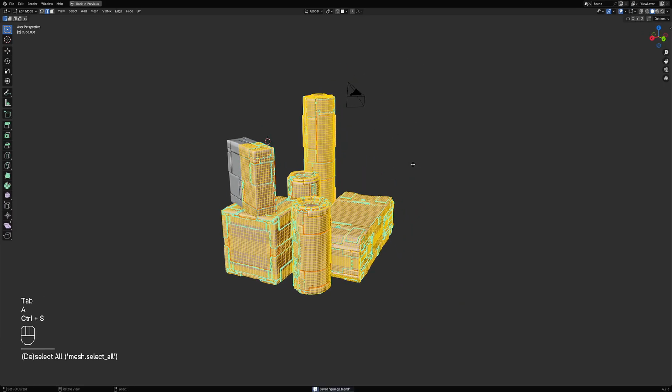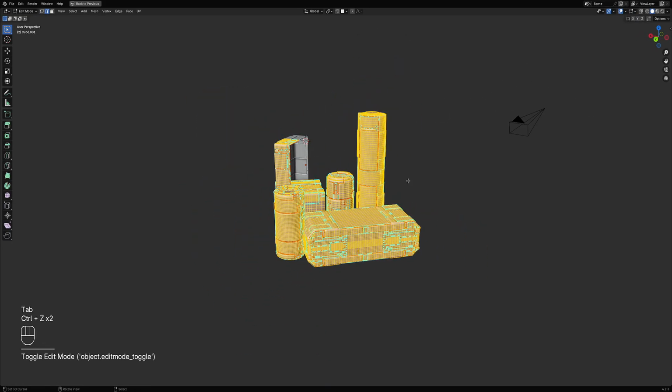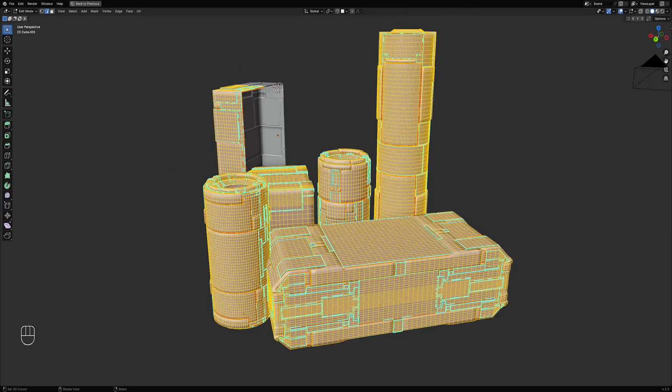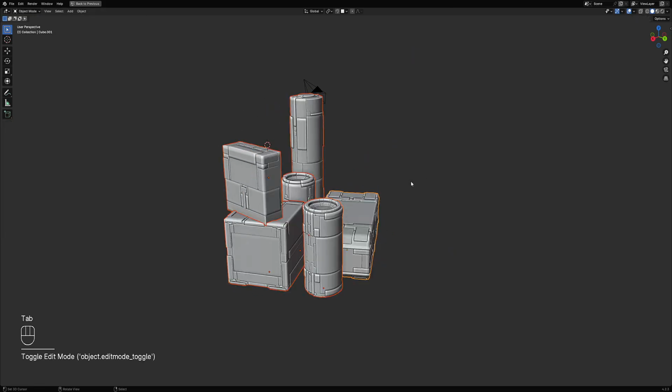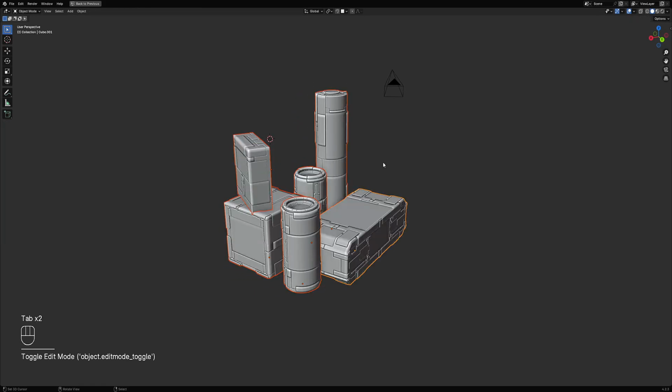Okay, let's lighten this by using limit dissolve. Oh, if you limit dissolve, the random shading gets really bad. So if you want to keep the random shading, be sure to keep the quad structure as well.